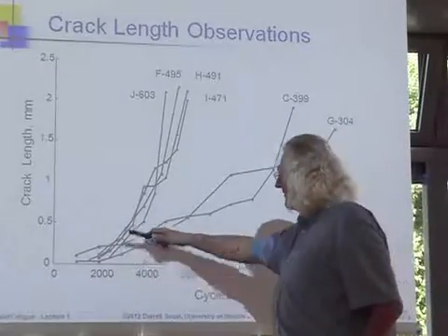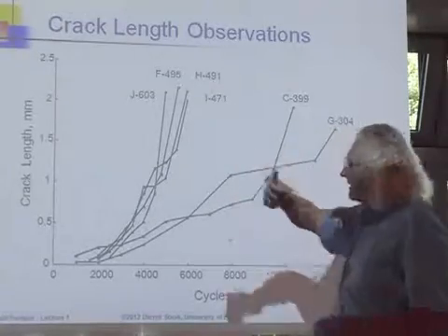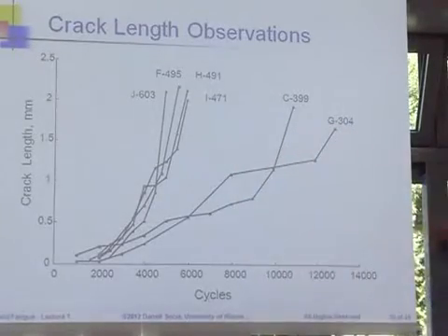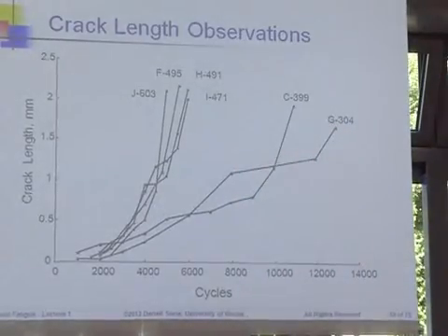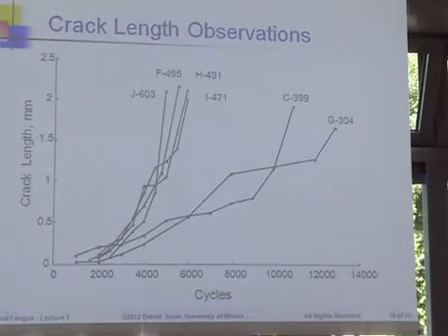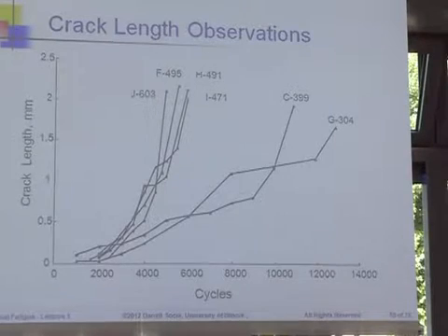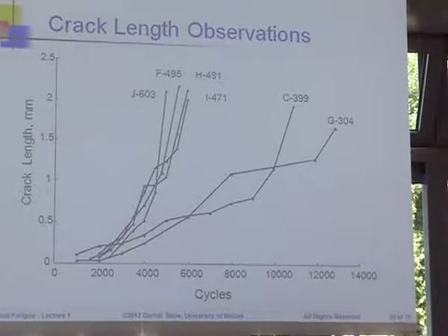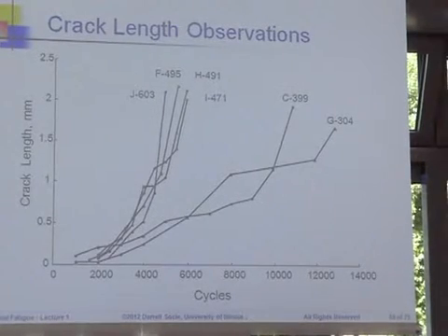Very small. And once the cracks get to be a millimeter or so, then they grow very quickly to failure. And that's what always happens whenever you look at something on the size scale of this for the test vessel. So almost all of the lifetime is taken up in forming cracks, which are on the order of 1 millimeter or thereabouts.